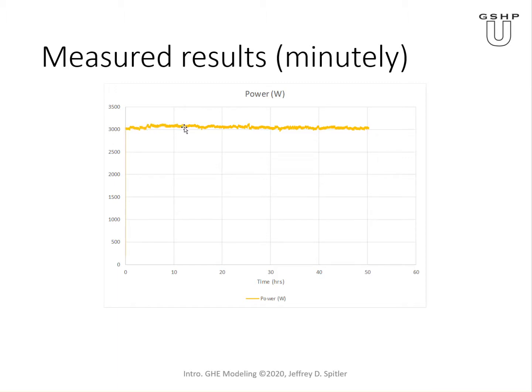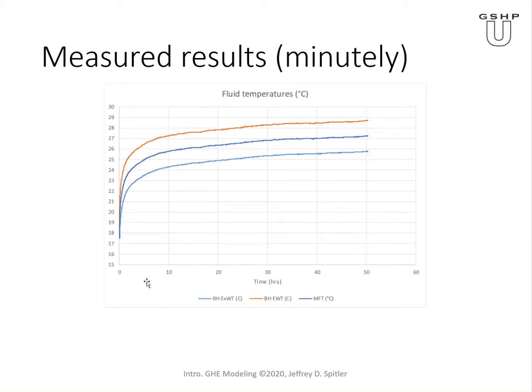This test is actually pretty good. You see it's a bit higher early on, around 10 to 15 hours, and it drops off, comes back up a little bit again. It varies, but it's pretty well maintained. If we look at the temperatures, we've got the mean fluid temperature, this middle curve, and the temperature exiting the borehole. So we're putting warm water in, that's the input, and then it comes back out somewhat cooler. It's a fairly smooth curve, and pretty good test quality.